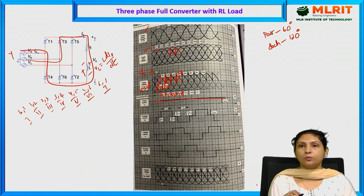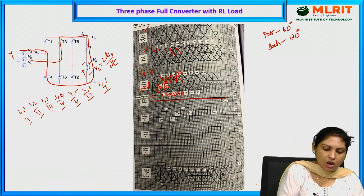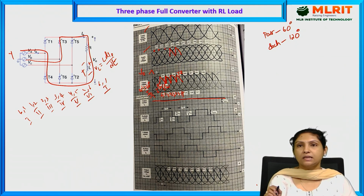And this output current continues and ripple free because of the very large value of the inductor which we have actually chosen. So this is nothing but our output current waveform. And now let us see the individual waveforms for current through R phase, Y phase and B phase.